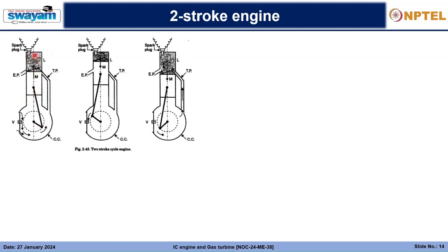So the piston eventually moves, and when it comes down, it is pressurizing the air fuel mixture out here. The valve remaining closed, it has only one way to go, through this transfer port to this pipe, and the air fuel mixture finally arrives here. The piston again moves up. It will compress the air fuel mixture and create a huge pressure. At this huge pressure, the spark plug will create a spark. It will ignite the whole mixture. It will produce the pressure required, and it will push the piston downwards. So that is happening.